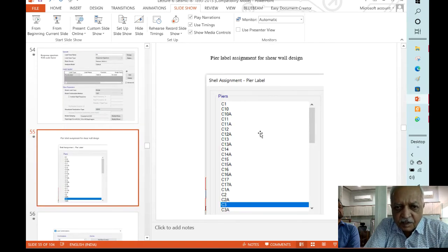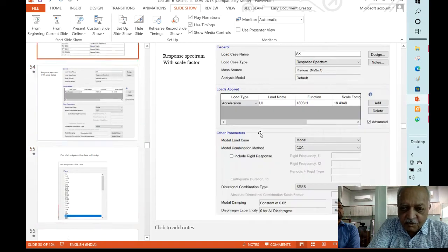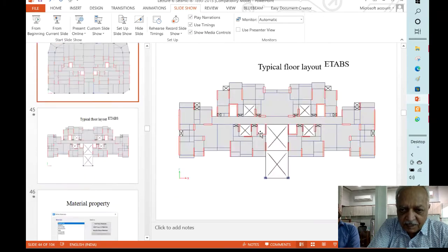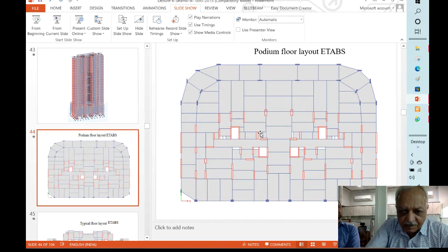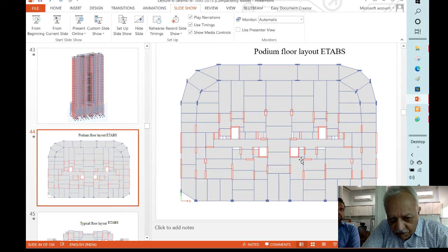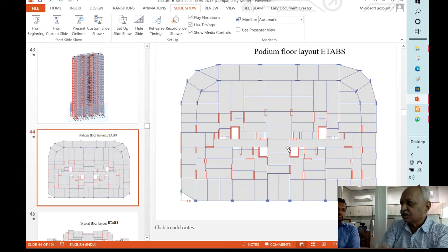Okay. Now when you are considering, for example, the plan of the building, then we see that for this plan, if you see this particular shear wall, which is in fact a lift well, now there are three legs to it and they are all monolithic. While individually you have defined one wall like this, another wall like this, and a third connected to that, all of them put together you have got one structural member. They individually might attract some force, but their action is combined.